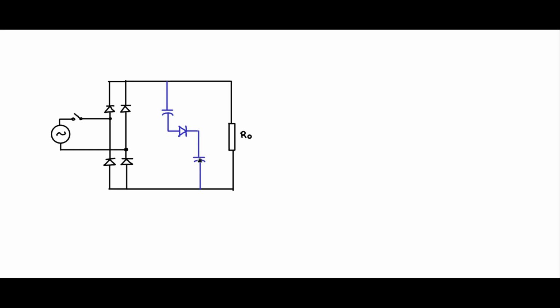Now when you want to discharge, discharge each capacitor separately. So provide the discharge path. You put a diode in this fashion. So this diode will give this capacitor a chance to discharge through the resistor in this fashion. And if I put a diode here, you will see that this capacitor can independently discharge through the load in this fashion. So while charging, the charge path is only in this way. The charge is divided equally between the two capacitors if the two capacitors are equal, and the two capacitors will independently discharge into the load. So the diode steering network takes care of this issue.